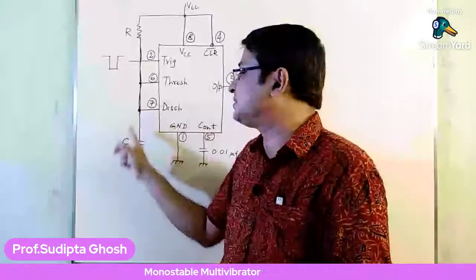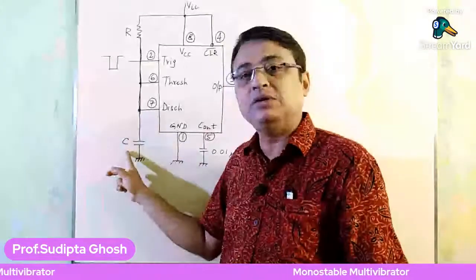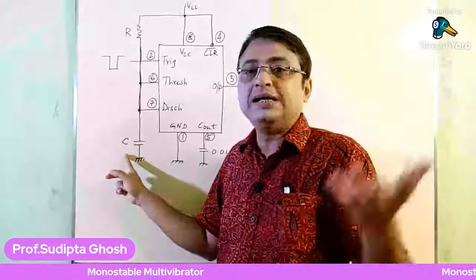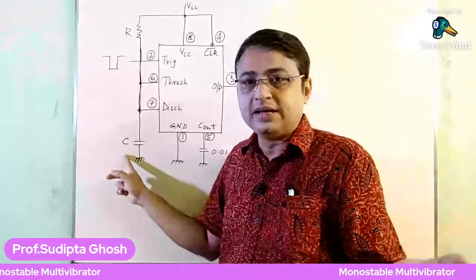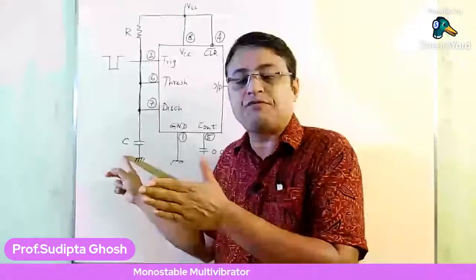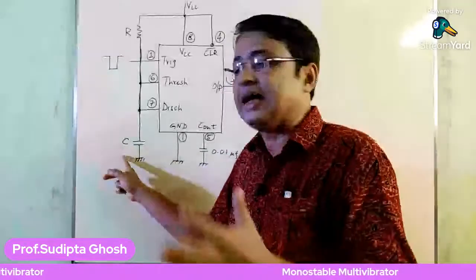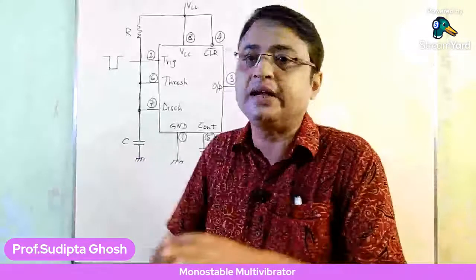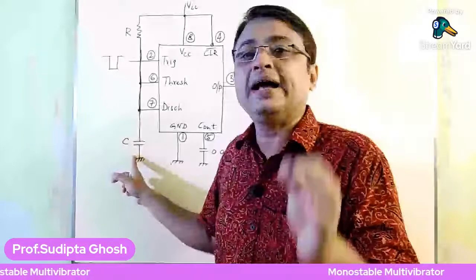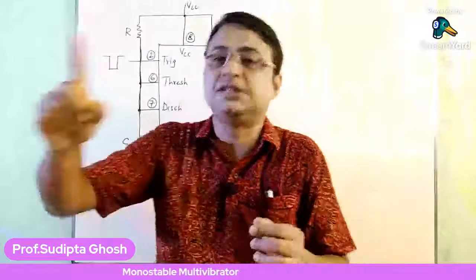Pin number 7 is connected to the capacitor itself, and the capacitor value is right now 0, because the 555 timer output was low, at its stable state. So now this capacitor is virtually disconnected from the discharge pin, not actually disconnected. But as it is virtually disconnected, it will again find the value of VCC, so again the capacitor starts charging.